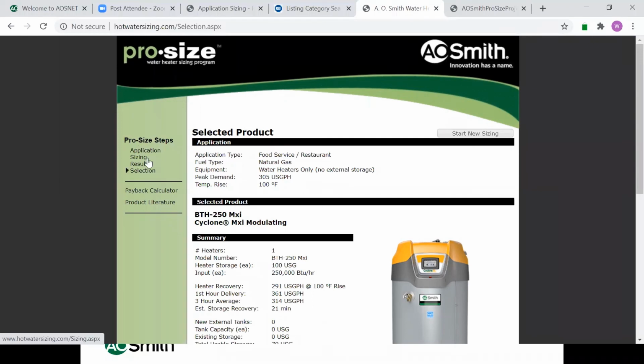Yeah, and I think that's a good point to tie into, again, that question regarding the ASHRAE fixture units and the OBC fixture units, which we'll certainly investigate the correlation there between the two and get back to everyone with their feedback. But with ASHRAE and really with the modified Hunter's curve, that was done by kind of doing what you're talking about there, of talking to the individual locations, but on a massive scale.